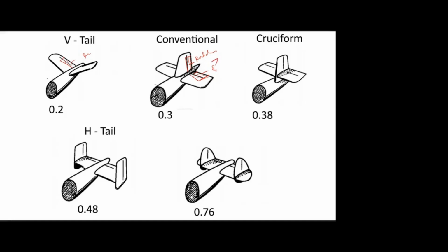So in the conventional type, there is a separate control stick for the rudder and elevator, so for the pilot, it is easy to control. But in this ruddervator, simultaneously you have to control the ruddervator angle, and you have to change it to do the maneuvers. So the controlling is difficult if you use the ruddervator.